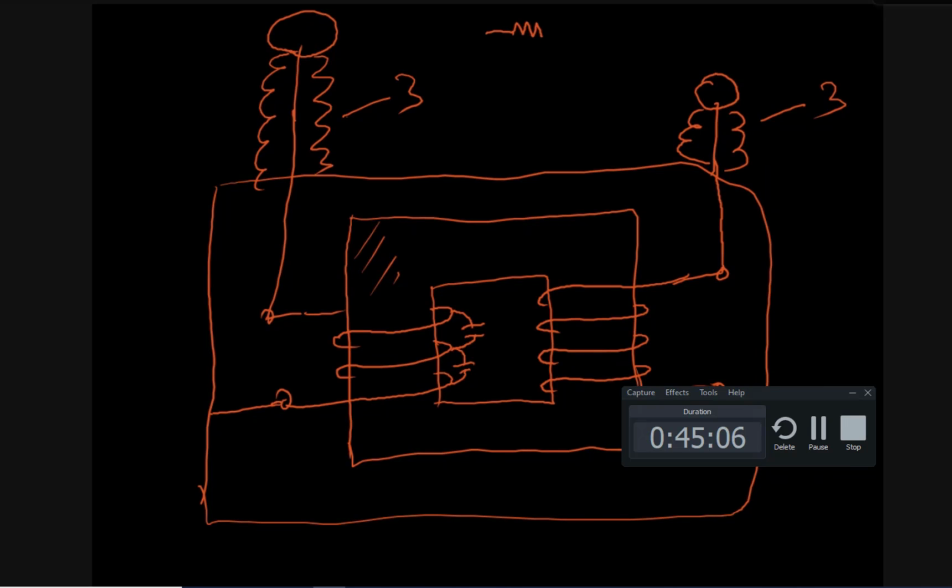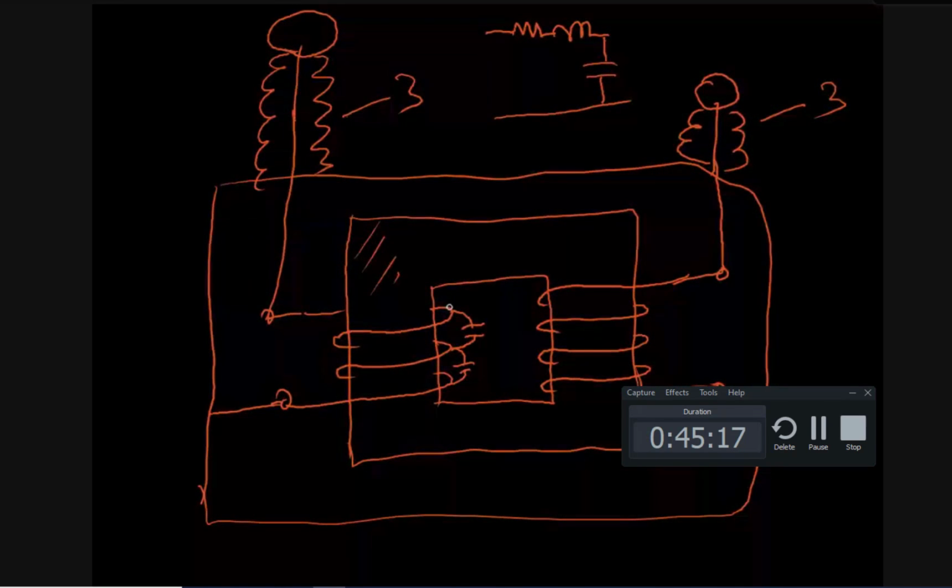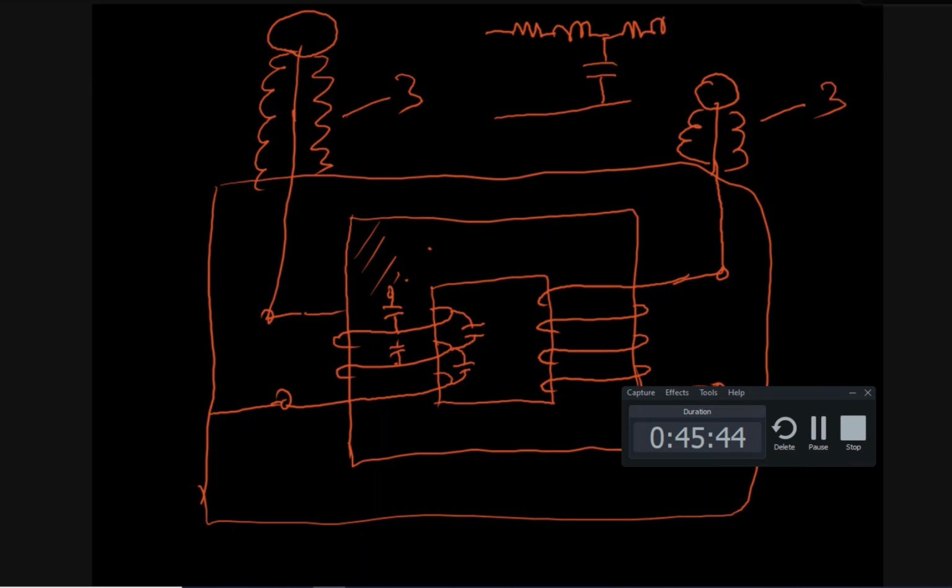So a series resistance, I am drawing simply; actually it can be complicated further also. And then capacitance to the core, of course. Each winding wire is separated from the core by some insulation. Therefore, the core will act as an electrode which is normally at ground potential, and the winding is at high voltage potential. Therefore, there will be capacitance to the core also from each winding turn. So this is the parallel capacitance given here, and then resistance, and then inductance.